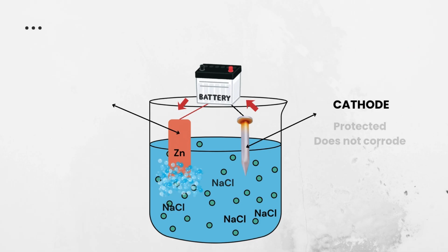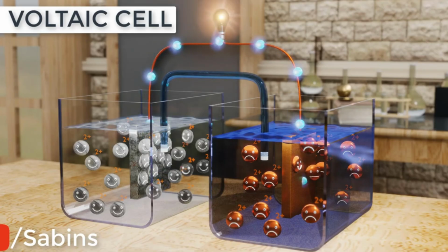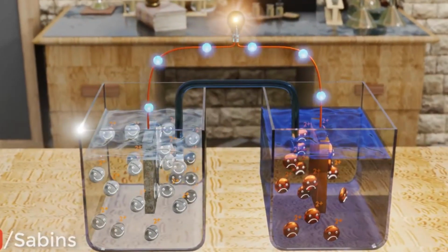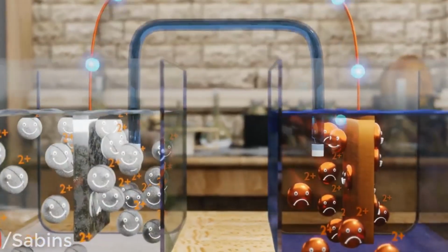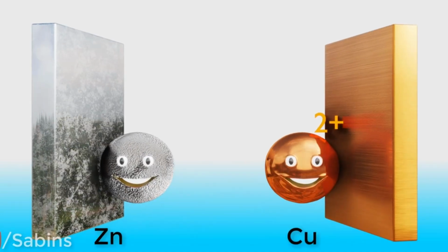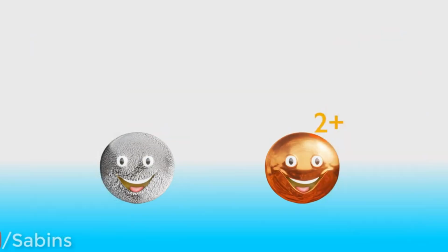The ICCP system protects metals by controlling the applied potential. Induced electrochemical process: the metal receiving electrons from the battery becomes the cathode and does not corrode. The metal connected to the positive terminal becomes the anode, and thus corrodes. Key results: the iron almost completely stops corroding. The zinc shows heavy bubbling and accelerated corrosion. The multimeter shows higher current due to the externally applied force.